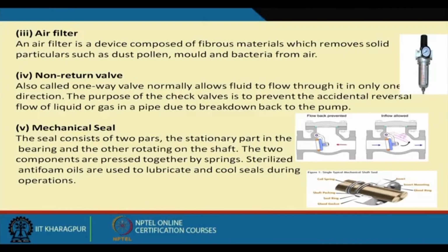We cannot tighten it to the maximum, because if you tighten it very much, then the friction will be very high, and if there is more friction, there will be more heat generation, and if the heat generation is more, it may rupture the mechanical seal. So what we do in the industry, we pass the antifoam oil,